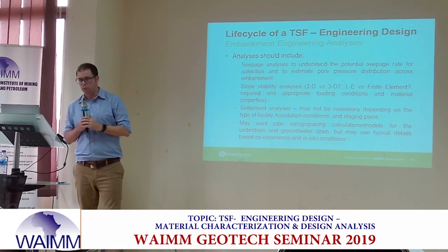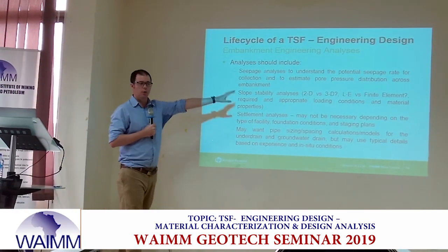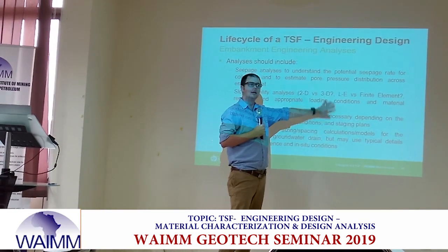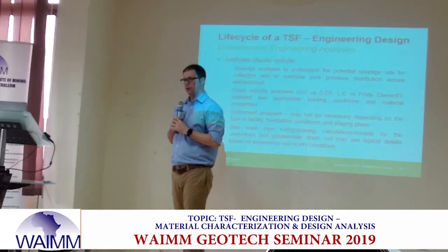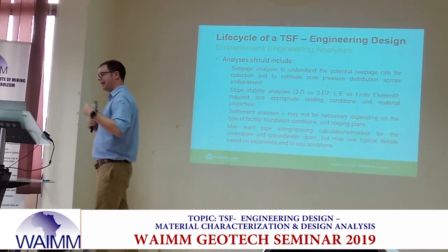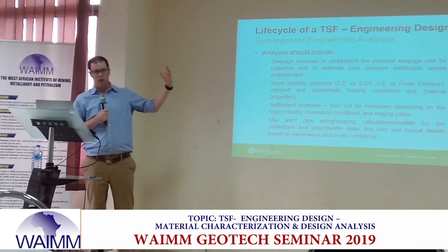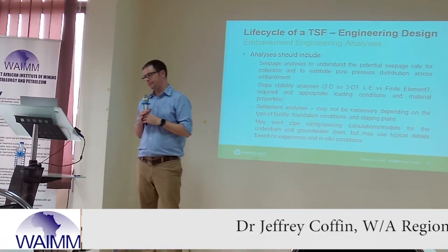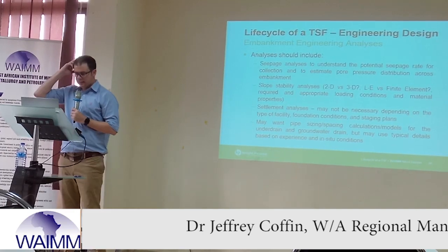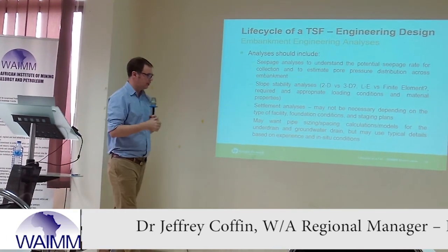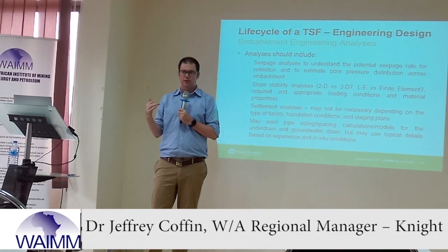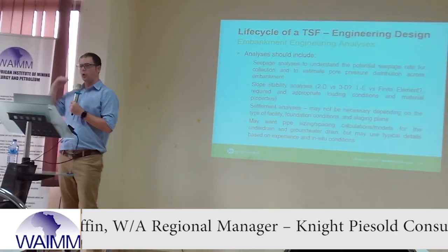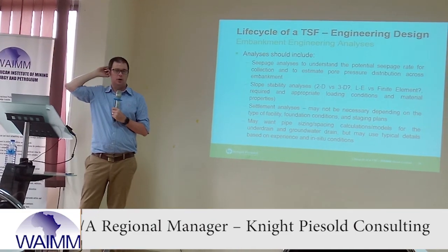If we're at 1.7 exactly, but we're not super comfortable with the site investigation work that we've done, maybe we want to do some more sophisticated analyses, but we only do more sophisticated analyses when we get more sophisticated material properties to justify it. We may look at settlement analysis. Because we're continually constructing these dams, settlement is less of an issue, right? Because if we lose maybe 10 centimeters, we're just going to add it back on when we do our next round of construction.